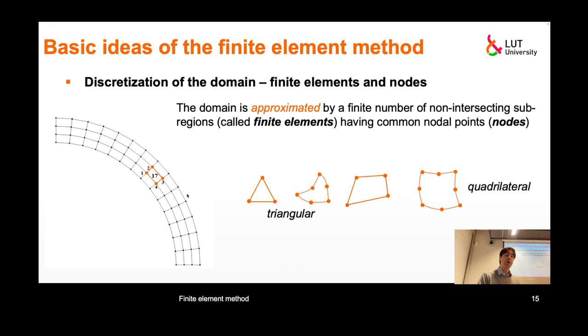For instance, if you are looking into contact interaction between this outer boundary of my domain and some other body, then you might see some very peculiar results if you use linear approximation here, because you will have some kind of angles there on your surface. Okay, just keep in mind that you are approximating the geometry. Not only what's happening inside, the distribution of the function that we are looking for, but also the geometry.